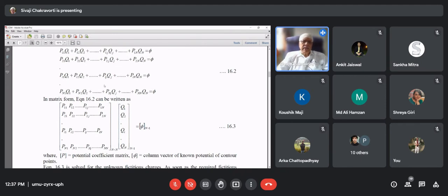Another very interesting aspect that you can see from this is that these Pij's are all related to coordinates of charge and point. So therefore, they are not zero. They have certain expression. Depending on the coordinate, I can calculate this. So this coefficient matrix, which is an n by n matrix, has no zero term, which is completely in contrast to FEM and FDM. I have explained earlier that FEM and FDM have mostly zero elements, and that's a sparse matrix.